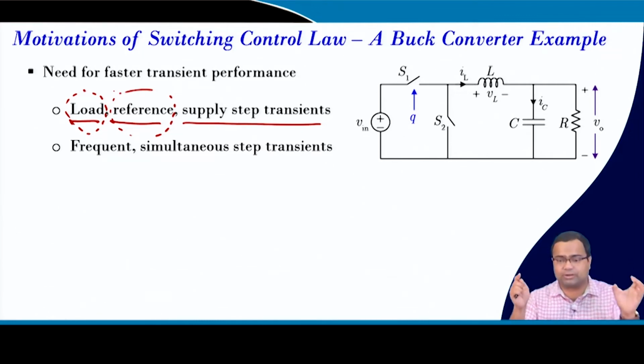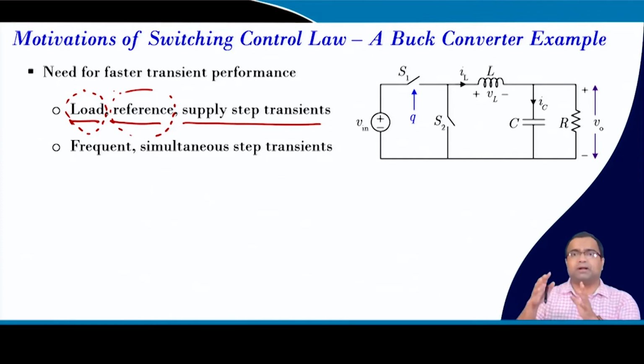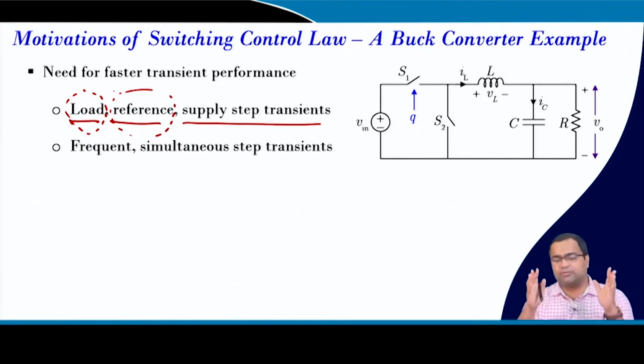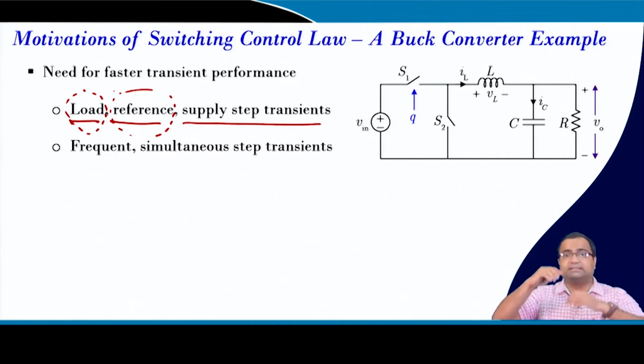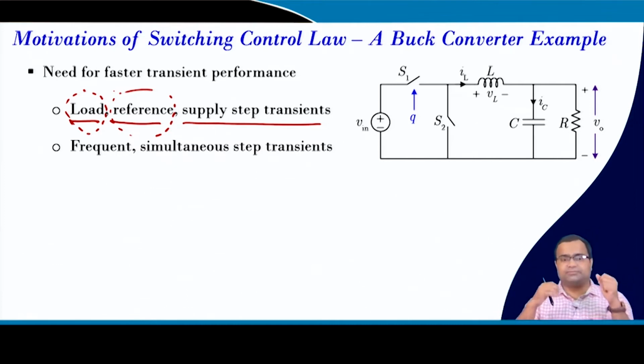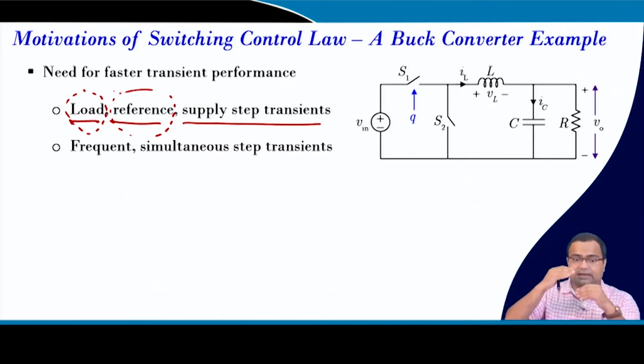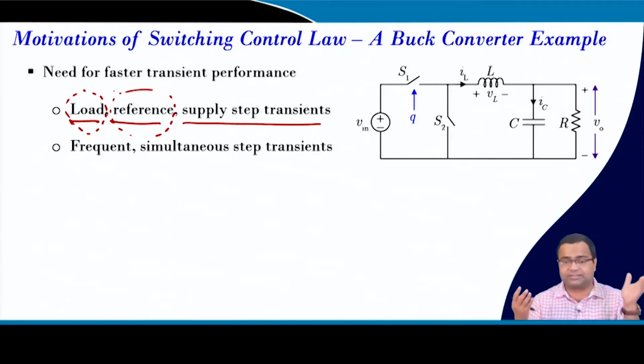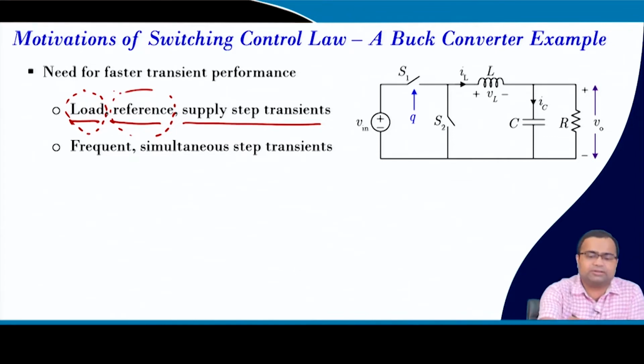That means if we talk about a cascaded converter, for example for constant power load, like a 40 to 1 volt application, there is an intermediate bus converter which can be a normal buck converter or an isolated converter, followed by a multi-phase converter. In the first stage converter, when you want to optimize the DC link voltage, you need a reference transient for the first stage converter. Similarly, for the load stage, if we want to change the VDD of the digital processor, then we need a supply transient, a reference transient for the second stage. So, this is also very critical.